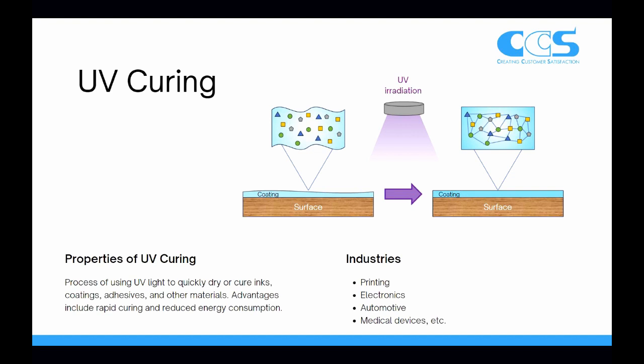A lot of places will UV cure pieces together with a glue, and then they UV cure that glue to make it stick together, put an epoxy coating on, and UV cure that over everything. It's pretty common in a lot of industries.